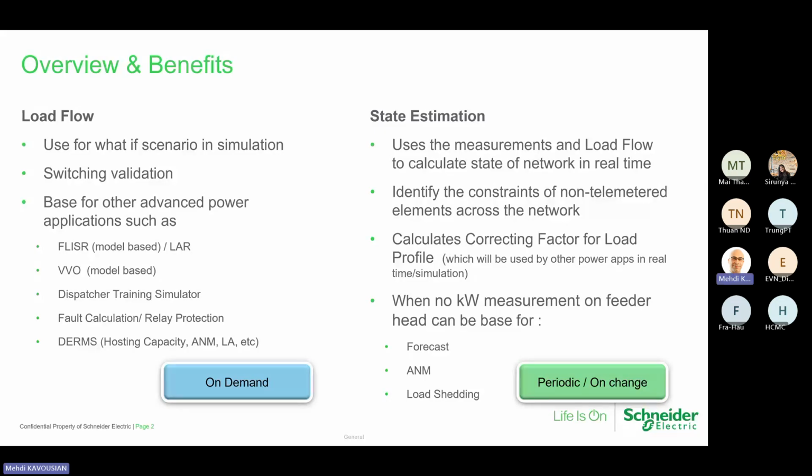What is the difference? With load flow, you have a load curve, right? Serenia was showing you the other day, you can have a load curve. That's for a predefined scenario, as an average, a typical day. But some days it might be different for whatever reason, so the measurements change. State estimation uses those measurements and adjusts the load flow results to be close to the measurements where they can be, so it makes the load flow results more realistic and more accurate.